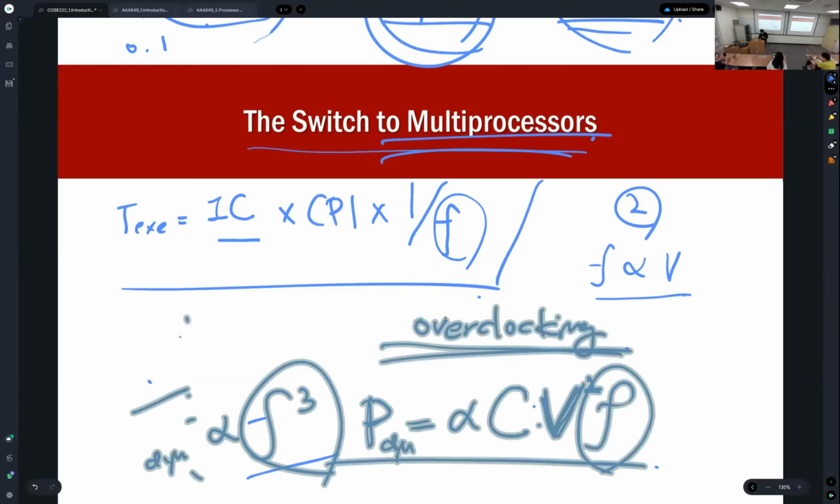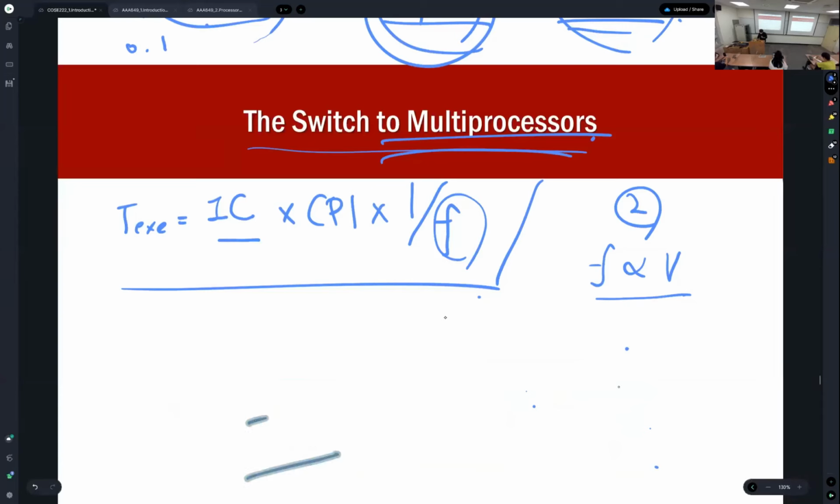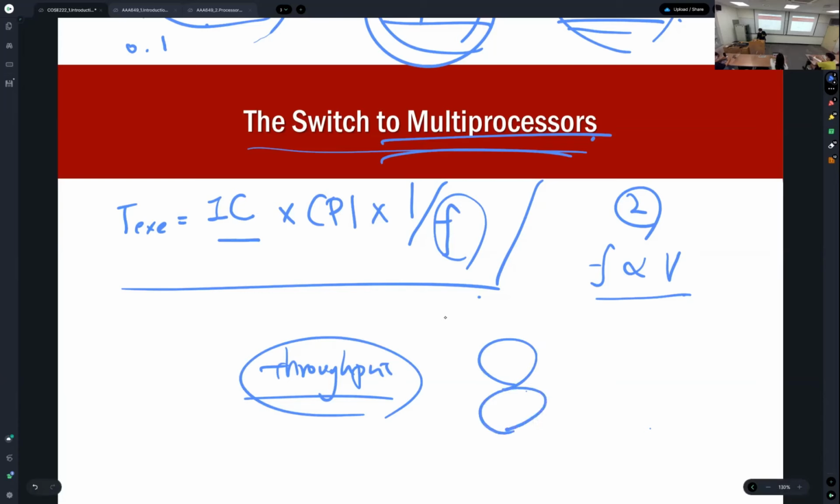So as I explained, increasing the clock frequency is the easiest way to increase the performance, I mean the latency, but it requires higher power consumption. But we can increase the other performance measure, like the throughput, right? For example, if we use a dual core, which means that there are 2 cores in a single CPU chip, and a core is an independent processor that can execute an independent thread, then with the 2 cores, the theoretical throughput is double.